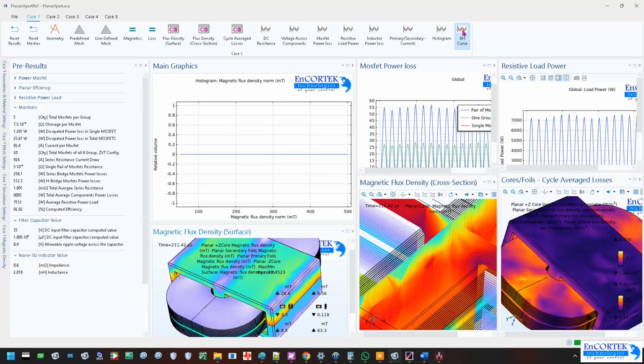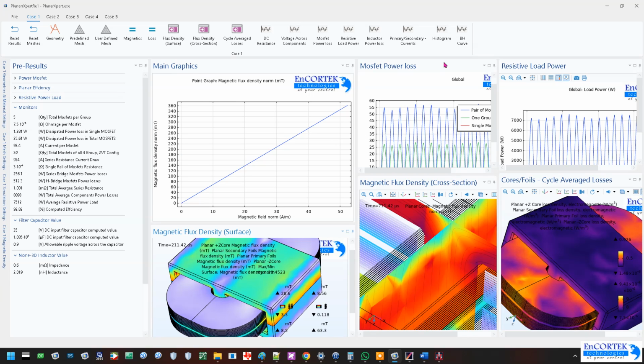And then we had a BH curve. Now I'm not using the BH curve on the data sheet because it takes more computational power for no big difference in results. So I'm using the core material permeability to do calculations, so it will be a straight line and not the BH curve you see, because you have to take the manufacturer's BH curve, use a digitizer, which is not a problem, to get that data out and put it into this. But the resources, time and computation just to have a little difference in results make no sense. So this could work pretty much fine.